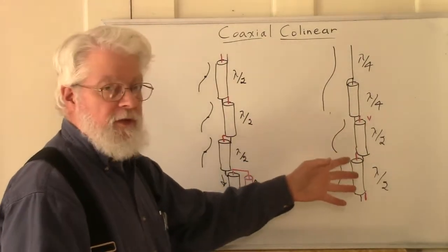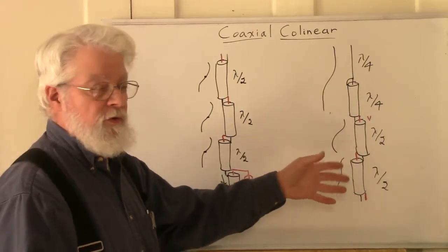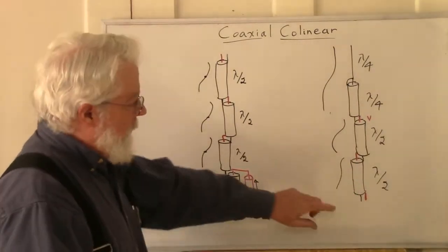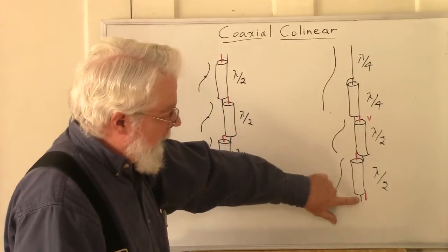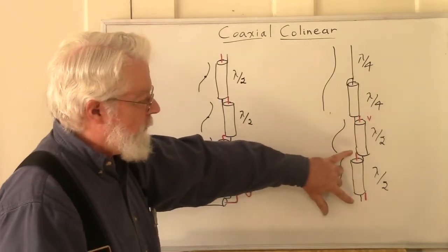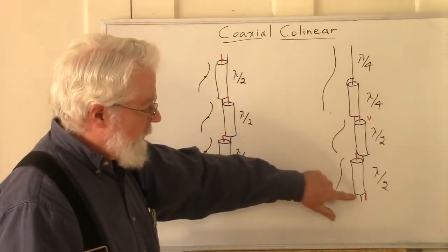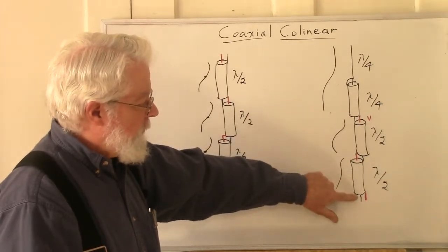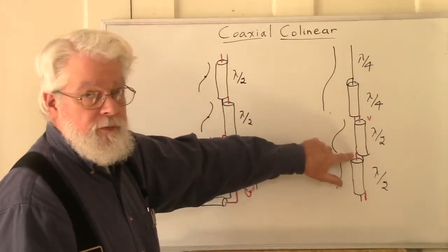The coax's velocity factor is always going to be a smaller number. So it's crucial that the length of the coax account for its velocity factor in terms of transforming this 180 degrees.